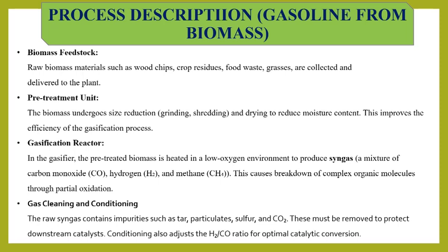And gasification is a process whereby the biomass is heated with limited oxygen to produce syngas. Syngas is a mixture of hydrogen and carbon monoxide, and also methane, as we have here. This causes breakdown of complex organic molecules through partial oxidation. I have gas cleaning and conditioning.